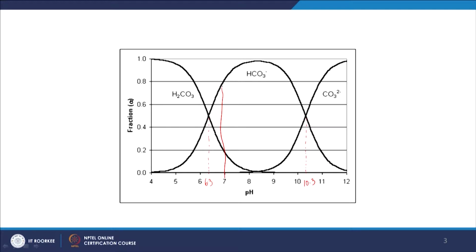So as we see, at neutral pH, almost 80% of it, as you see, this is the ionization fraction. And what do these ionization fractions give you an idea about? Let's write them down: alpha naught, alpha 1 and alpha 2. Alpha naught is going to be equal to the concentration of H2CO3 divided by the total acid, and we are going to define total acid, like we did elsewhere, as the sum of all the conjugate acid and base species.